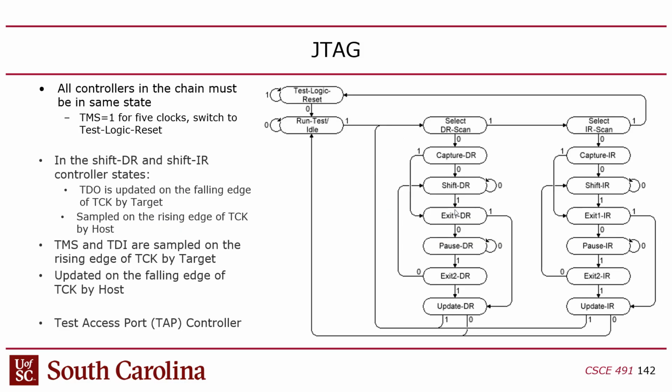So what is test mode select? This is cool. Test mode select allows you to put all of the chips on the JTAG chain in a particular state. And there are, I think, 16 states. Yeah, there are 16 states. This is the standardized set of states for JTAG.